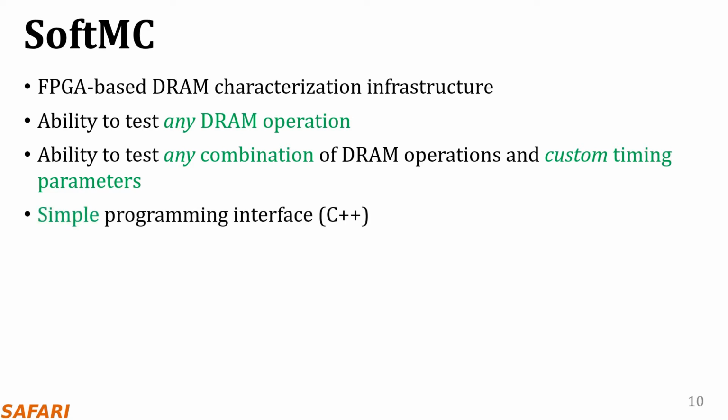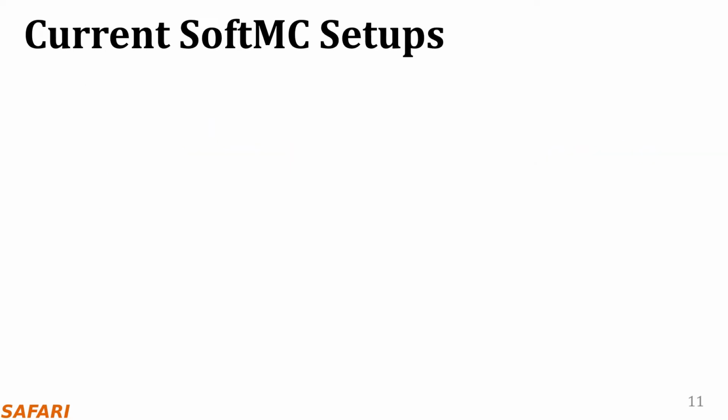This is all possible using the simple C++ programming interface that SoftMC provides. So users don't need to make changes in the FPGA application, but rather write DRAM tests completely in software. Let's see what the overall infrastructure looks like.